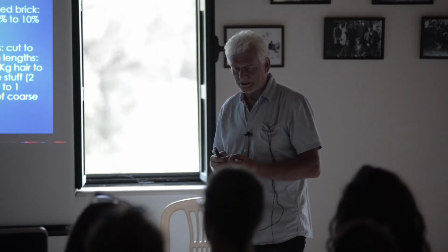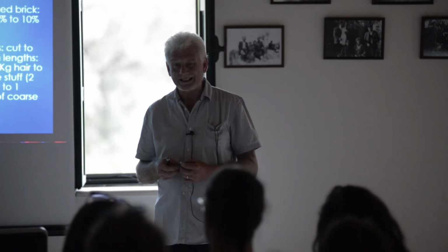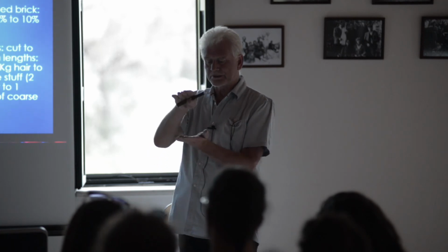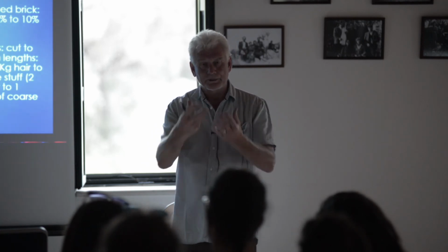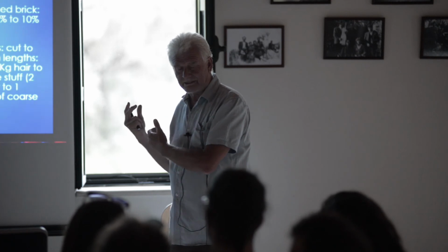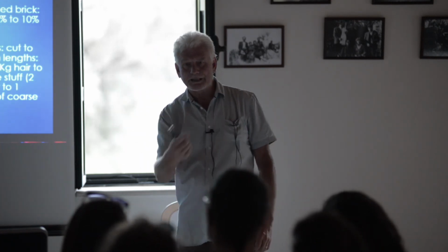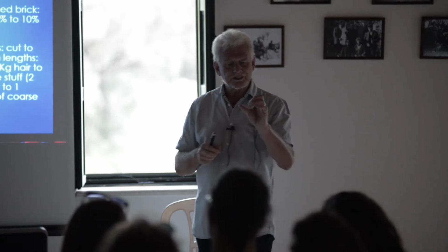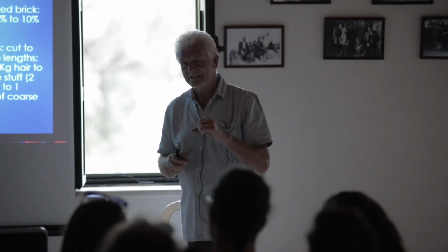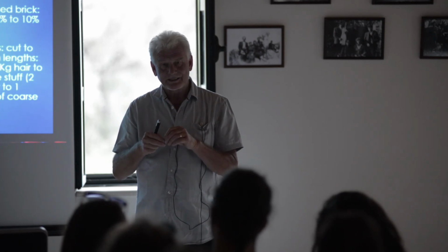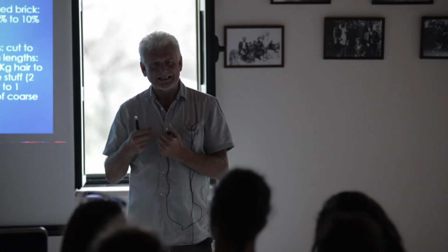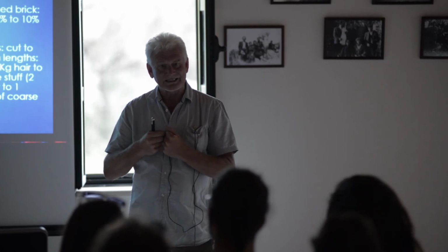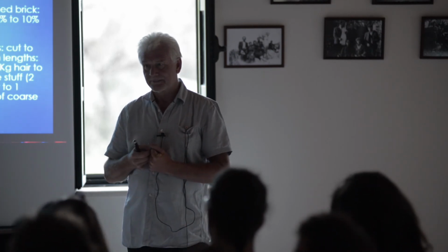The other thing about using crushed brick, let's say in a mortar between two stones: when it rains, the water goes into the stone, it comes back out through the mortar. If you're using very small particles of brick, the water will be absorbed by the brick, and it'll be released much more slowly. So the breathability is actually improved.